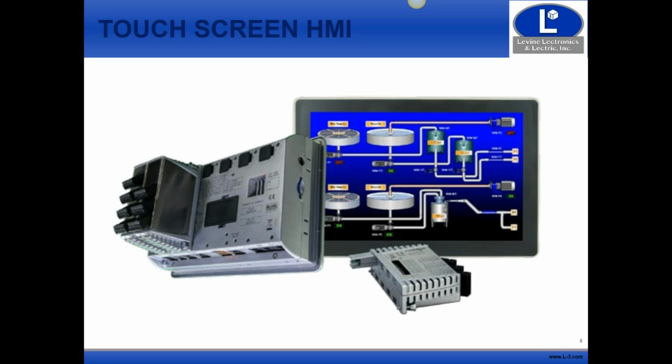And so there are times where it's going to be localized to just our cabinet, but there are also times where we've got to provide it to the building EMS. So what's really cool about this particular all-in-one solution is we can convert within here to any protocol we need. So this has our BACnet protocol built in, so we can convert that over